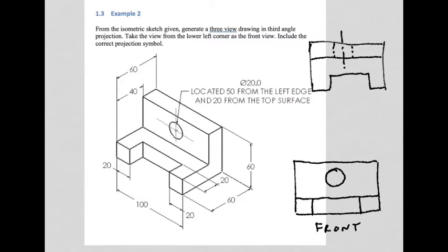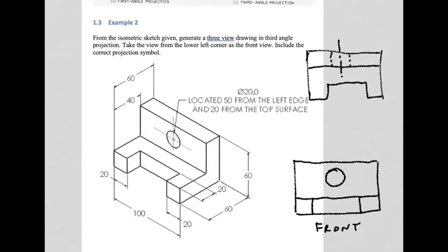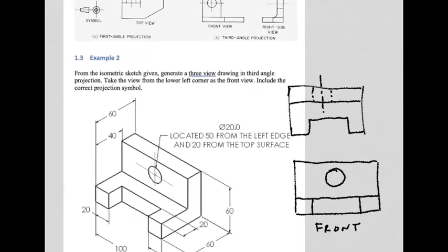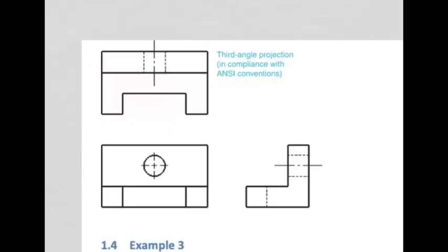Well, we've got to draw in third angle, and third angle says what I see from above I draw above. So back to our primary view. If we have this as our primary or front view, what we see from above would be what I've just drawn. We would have to draw it above over here. So it's a simple matter of positioning this piece, this feature, directly above the front view. So that would be the orientation of those. So the top view would go above,